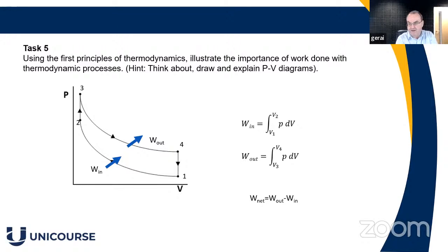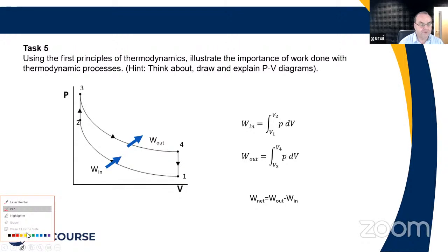It's just for you to explain what the usefulness of a pressure volume diagram is. I've just said before, the area underneath the graph represents the work done. If we look at this one, I'll do it in different colored pens so we can actually see it. If we look at the compression part of the process from 1 to 2, the area under that is the work done in the compression. So we can just shade that off to make it clear.